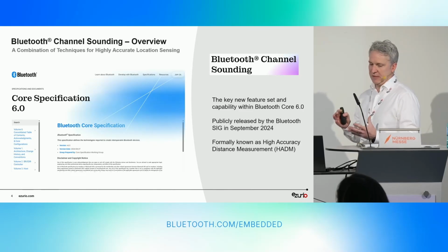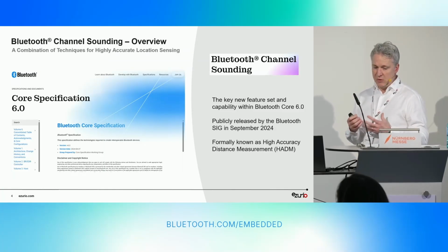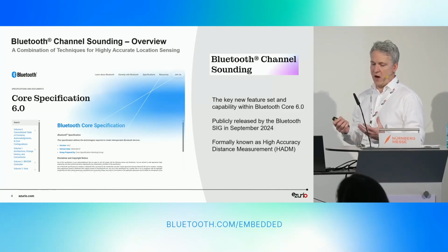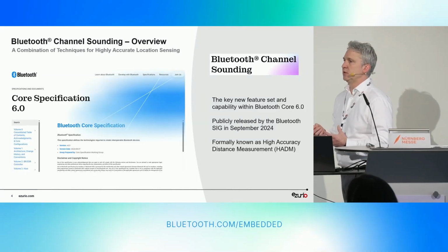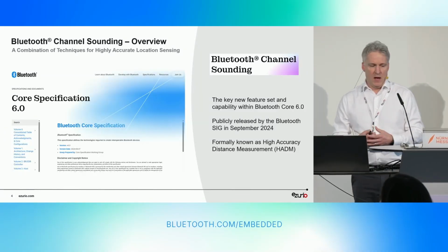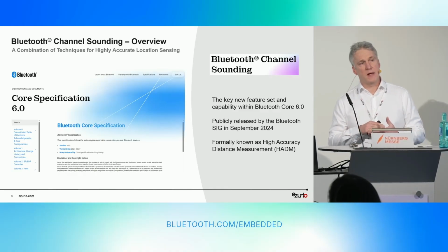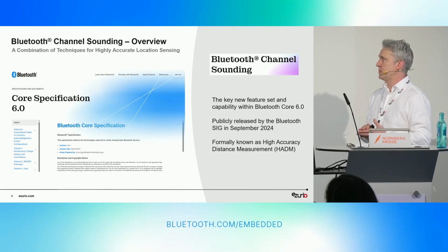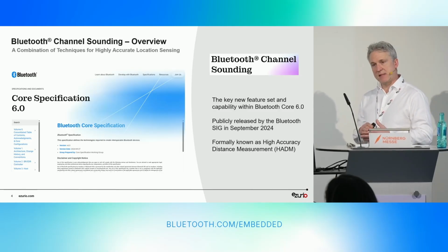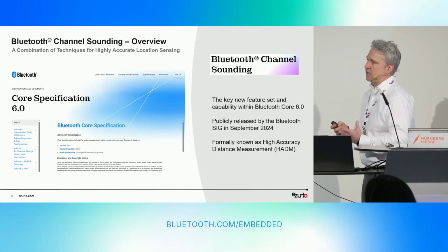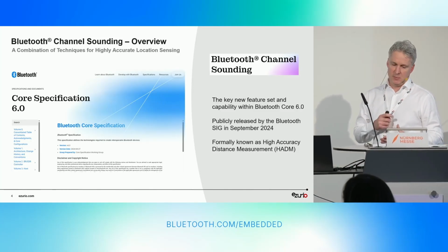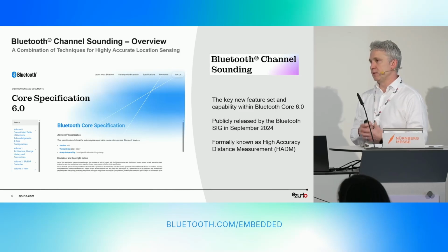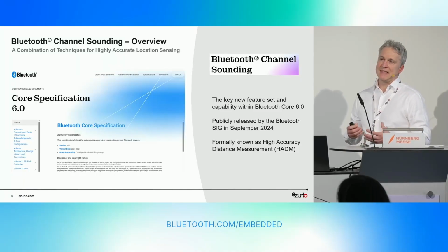In simple terms, it allows Bluetooth devices to understand how far apart they are, but with a level of accuracy that Bluetooth has not been able to convey before. And really introduces some new mechanisms, and we'll touch upon these: phase-based ranging, PBR, round trip time, RTT. It adds cryptographic detection inside of that to help improve the security and limit spoofing. And really what it's all about is multi-frequency measurement. The results, or what we're trying to achieve, is sub-meter accuracy, preferably in the tens of centimeters.